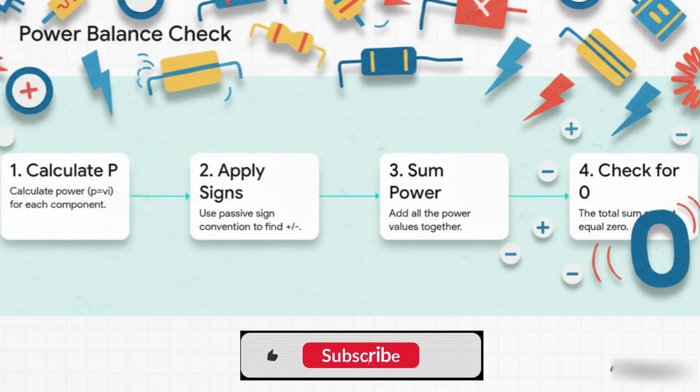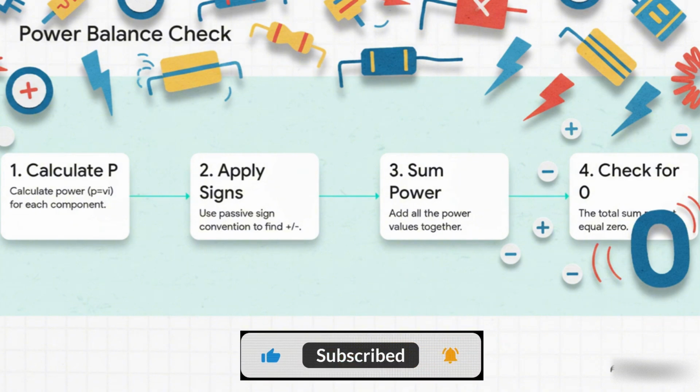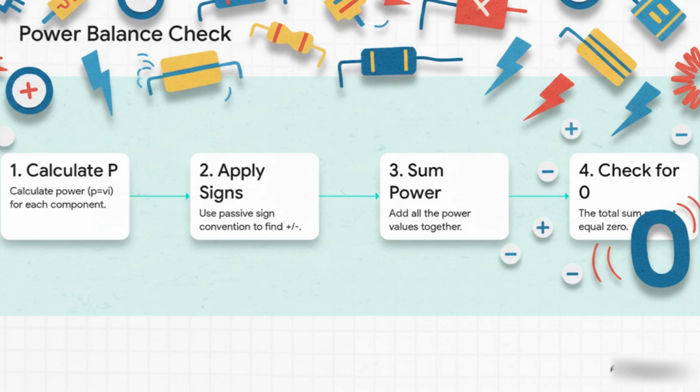So here's how you do it. It's a dead simple 4-step process. You just go through your circuit, one component at a time, and calculate the power for each one. You use that sign convention we talked about to make some positive and some negative. Then you add them all together, and if you did everything right, the final sum will be 0. I mean, it has to be, every single time.